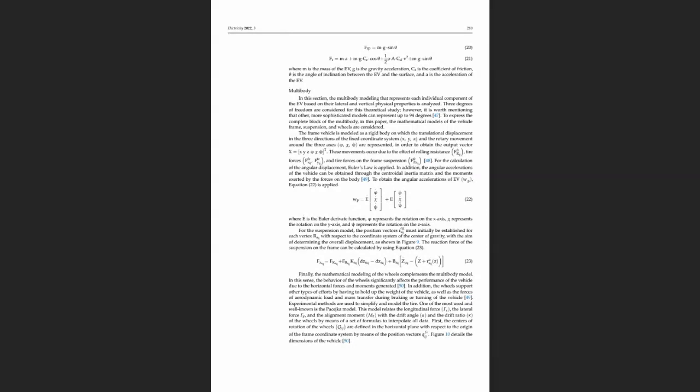It is not a torque, it is force. And then you will calculate Newton meter. After calculating the total force, you will obtain how much torque is needed for your electric vehicle. What's the methodology of it? It depends on your wheel radius.